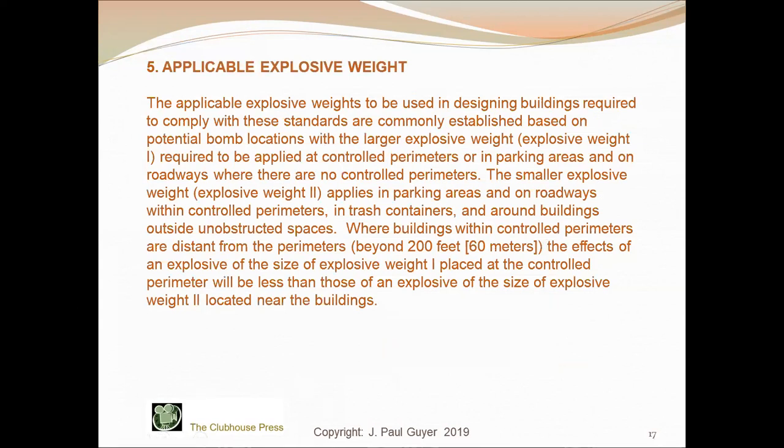The applicable explosive weights to be used in designing buildings required to comply with these standards are commonly established based on potential bomb locations, with the larger explosive weight 1 required to be applied at controlled perimeters or in parking areas and on roadways where there are no controlled perimeters.